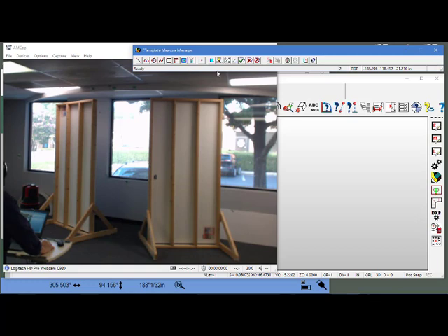Next thing I'm going to do is drop my construction plane to the floor. Select the point to lie on the parallel plane. So the construction plane was established at eye level, parallel to the floor. Because I'm going to do a perimeter here and extrude it up to a second floor, I want to do my perimeter at the floor level. So that's why I'm dropping the construction plane that's here now down to the floor. Now that we've done that, we're going to start doing a perimeter on the wall.